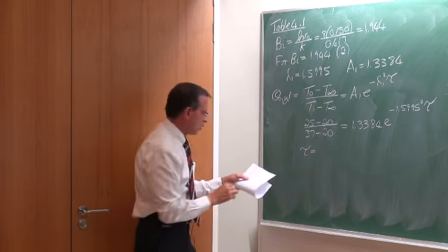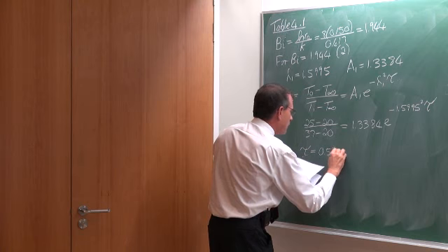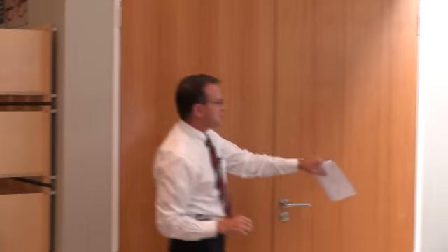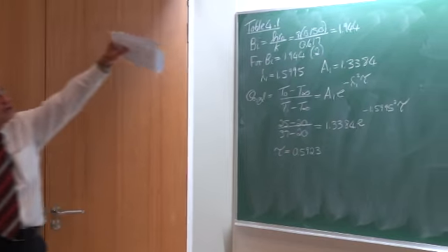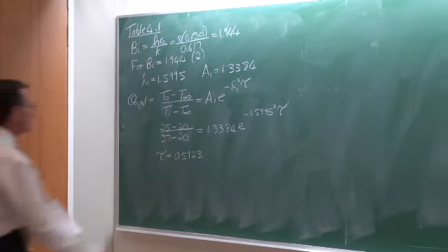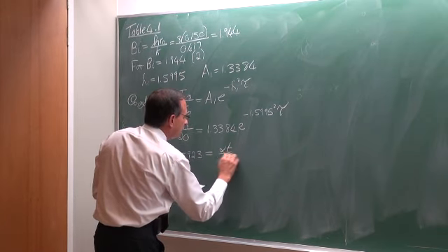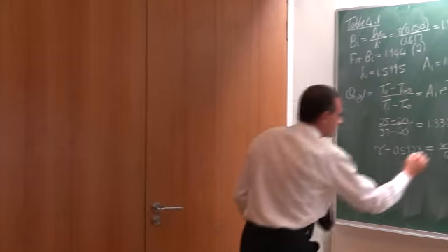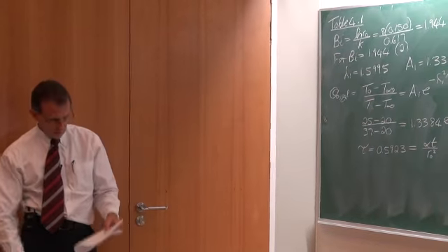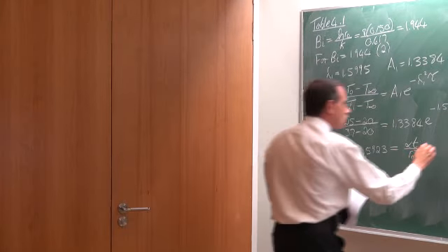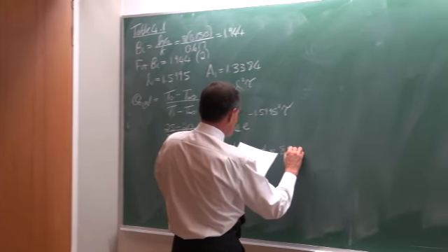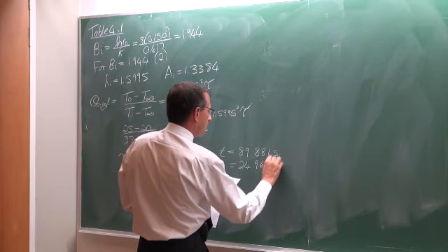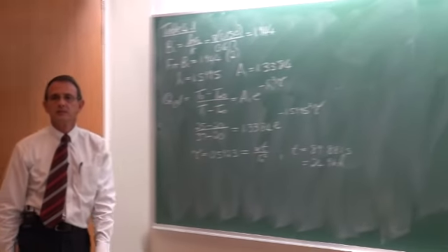From where you can solve that tau is equal to 0.55923, the non-dimensionalized time, which is equal to, and again, you don't need to remember it, alpha t divided by R0 square. From where we can solve that the time must be 89,881 seconds, and that is 24.96 hours ago. So it's almost 25 hours.